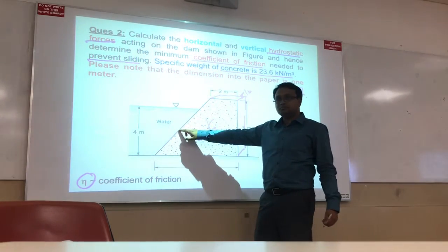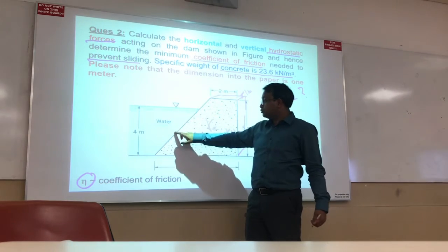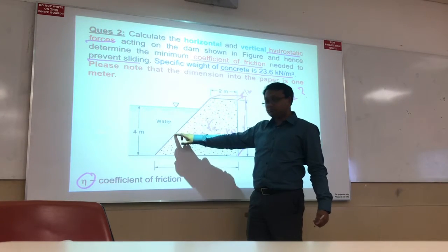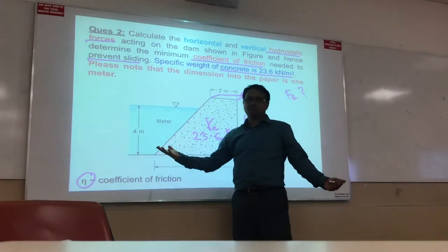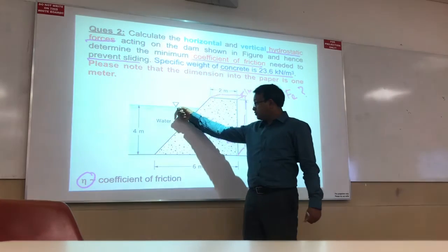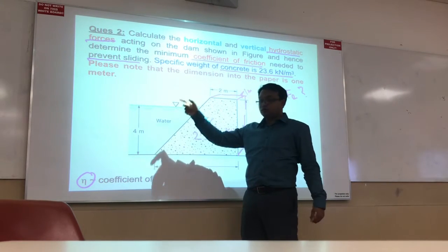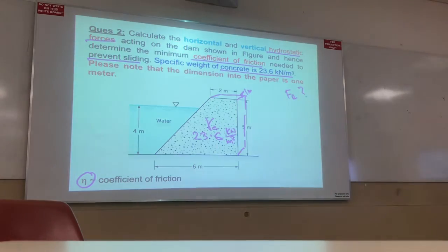Definitely here, right? I tell you the distance from the surface of the water to this point. So from here to here, what is the distance? 4 by 2, right? Distance is 4 by 2. So that means hydrostatic force F is rho g hc. Done. So I can easily calculate total hydrostatic force. No problem, right? Fr becomes rho g hc area.